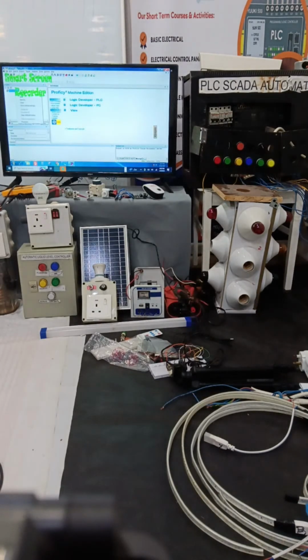Then right click, add target, GE Fanuc controller, VersaMax Micro PLC. I have the Micro PLC. Now this tree is already created. Here is the hardware configuration. This is by default the CPU number of the VersaMax PLC. Now we will create a program block. Now it is empty.